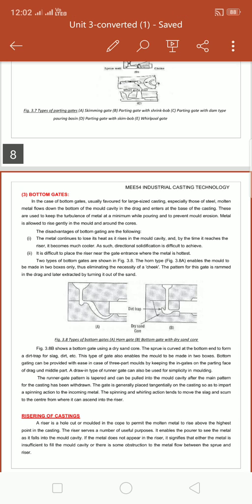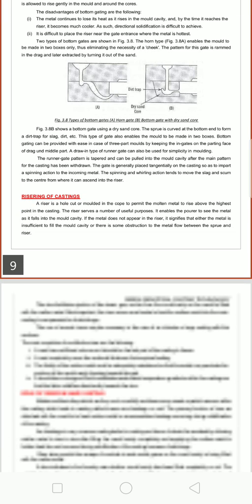Normally additives are added in very small quantities. Some of the additives used to enhance certain properties are as follows: cereal flour, which normally imparts dry strength and improves good quality. Up to 2% by weight of molding sand is added.